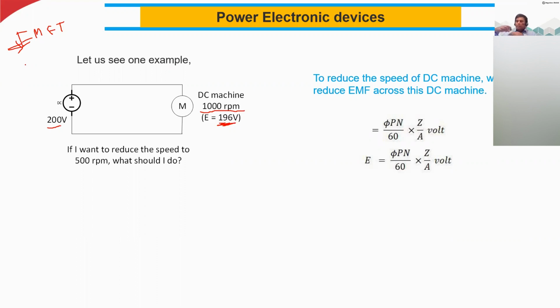And you also have the surrounding side, that is why we have an armature, either in a DC motor or AC motor. You have the center core and then the surrounding windings, so you have opposite polarity. The magnetic forces oppose each other, and then the rotor starts to rotate. That is the machine principle, which I'm not going to talk about now. How the rotor rotates is based on this electromagnetic force. So if you reduce this EMF, you automatically reduce the rotation of the rotor.